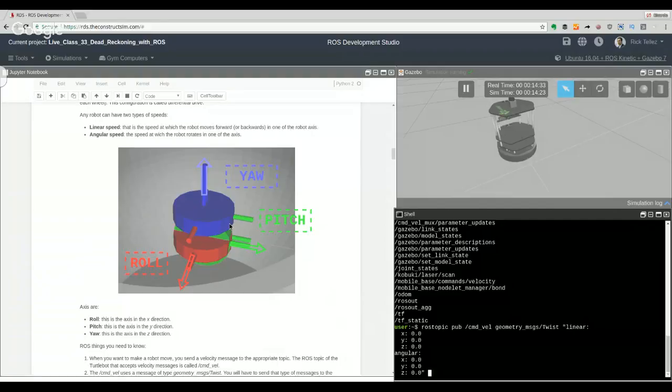With a drone, you can move up and down, so that makes sense to have it there. Not for this robot, but it's using the same message structure, the same type of message. And that's very good because we can share programs without changing the code. That's super cool. So remember that whatever you put on linear Z means nothing.